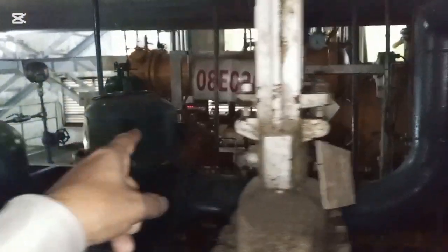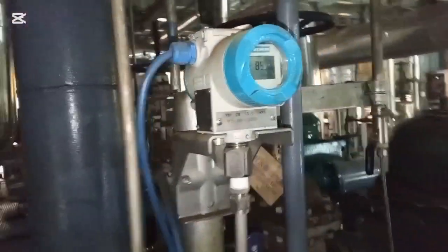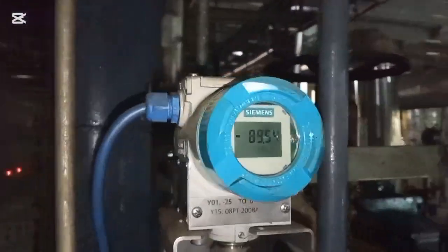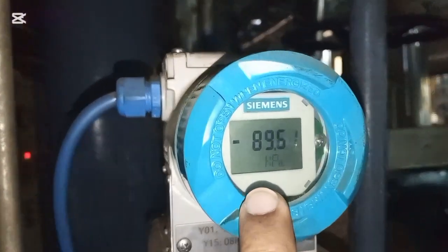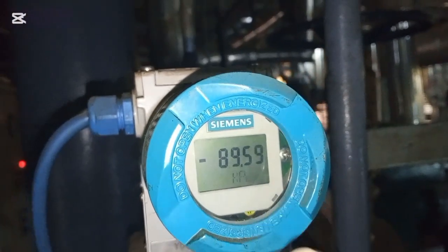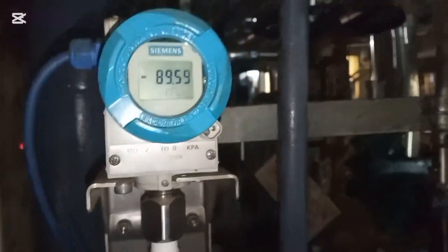Here are two ejectors, you see that one, and here is one and the parallel line, and here is also a transmitter. You can see this is the pressure transmitter. Here the vacuum is negative, that means minus 89.59 kPa, because the turbine is running now. And you can see this is the turbine line, this one,